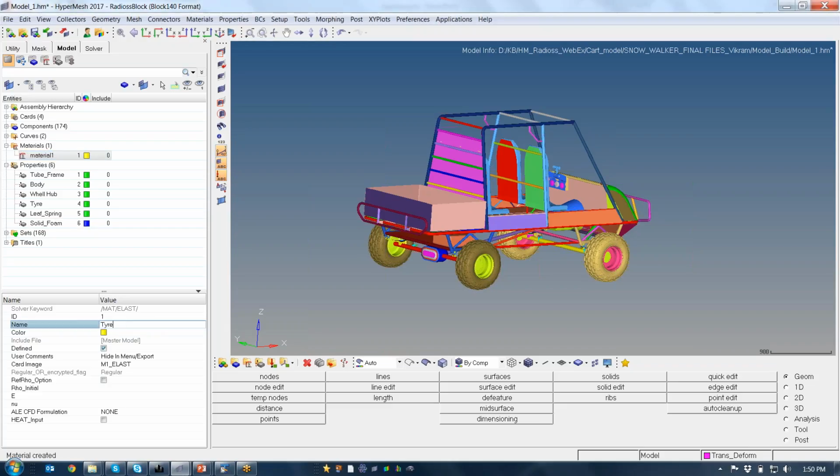So it's just a tire, elastic, and I will use a density near to the hyperelastic material, Young's modulus, and a Poisson's ratio near to incompressibility. Fine. Okay, so I created one material. This is the Law 1 material, which I'll later use for the tires.